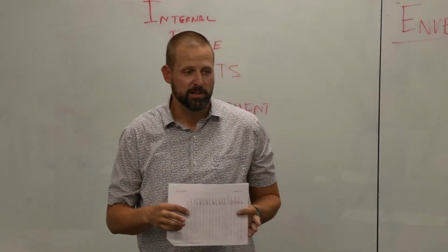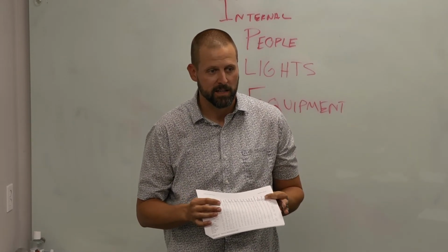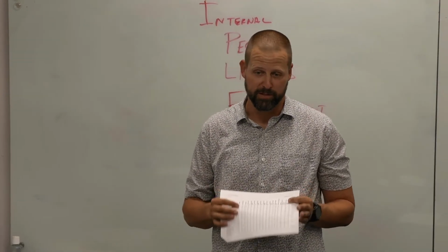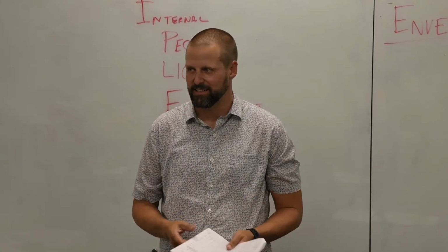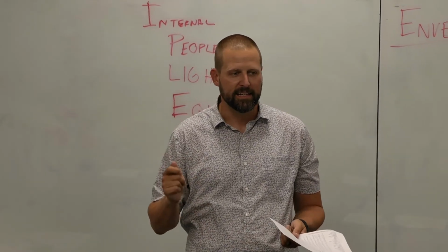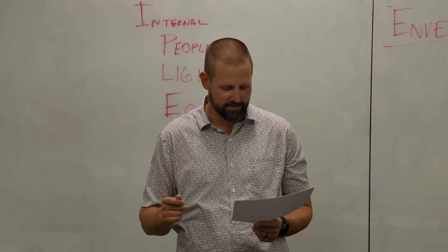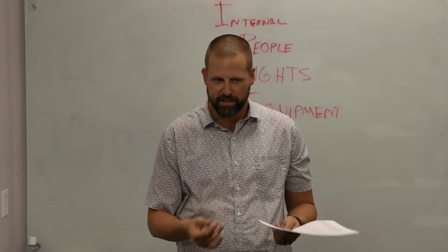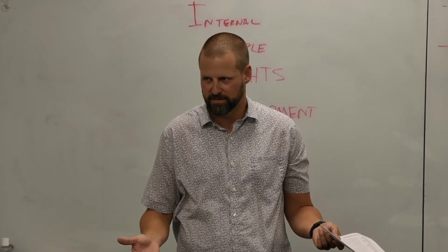Code allows healthcare to use the 0.1% data. Code also technically doesn't allow office buildings to use the 0.1% data, which is kind of interesting, and it's a bit of an ethical dilemma. So in theory, if you have an office building, you can't design above the 0.5% cooling data. From a practical standpoint, we are not going to short our customers on air conditioning.